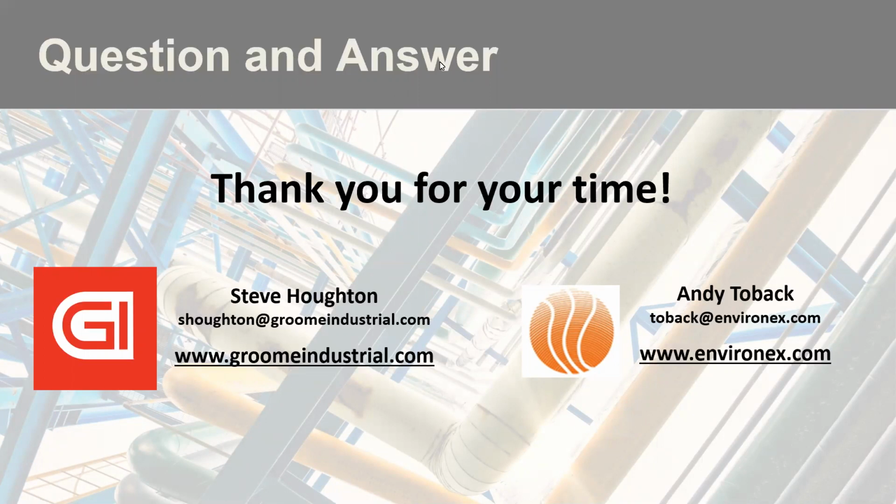No, we'll take care of all that. So the stack tester would measure your ammonia slip at the stack before or after. I mean, preference is after to let you know of where we're going to leave it. And then also a few times during the traverse testing exercise, measure what the NOx is before the SCR. So we'll be able to put all of the graphing that you see together that we showed today, like the surface plots, and we'll measure those values during the tuning. So you wouldn't have to worry about buying those analyzers just for the sake of tuning.